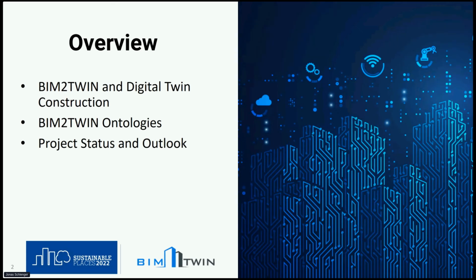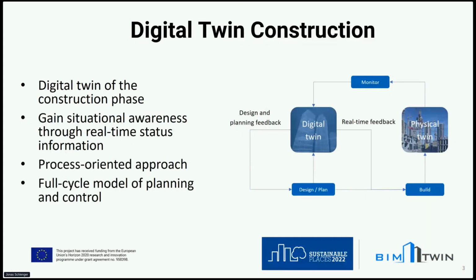So to dive right into the topic, the BIM2Twin project is focusing on a digital twin of the construction phase, as also the other projects that are presented here today. Our goal is to gain situational awareness of everything that is going on the construction site, and we really try to focus on the processes, capture when they start, when they end, if there are any issues, and compare what was planned and what was actually executed.